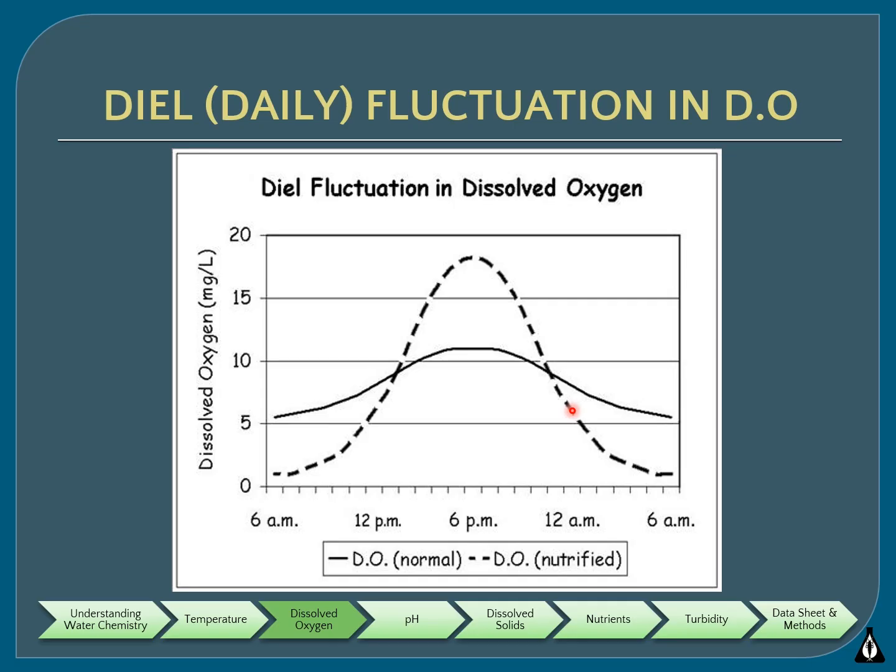The constant decomposition process requires oxygen. All of these factors together result in more oxygen being used at night than is physically added to the stream via aeration during the night. Therefore, it's normal for the amount of dissolved oxygen in the water to decrease as the night goes on, only to increase once again as the sun comes up and the plants start undergoing photosynthesis.